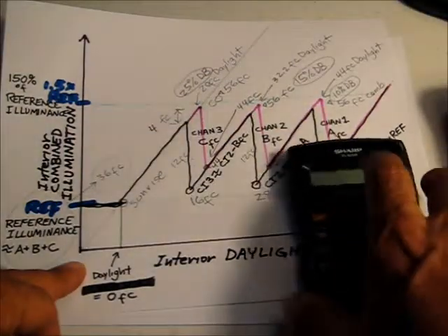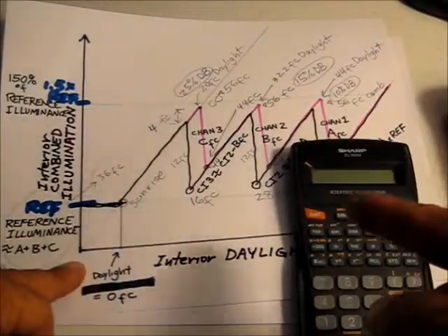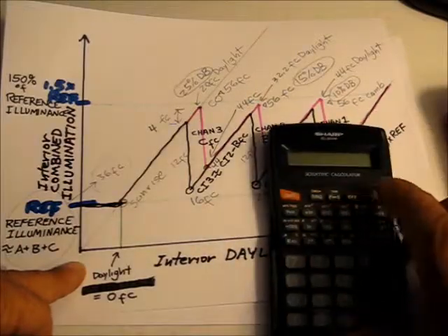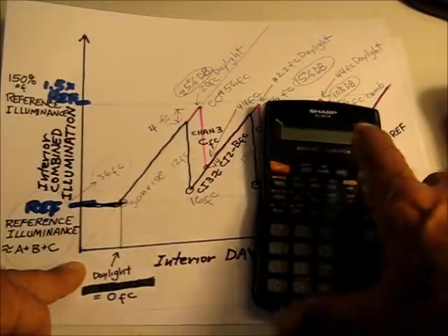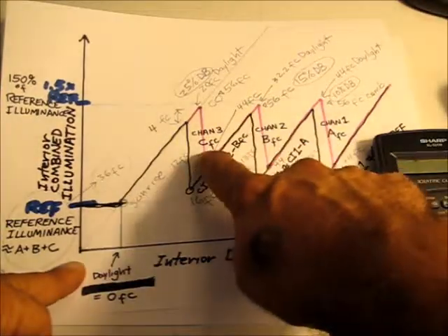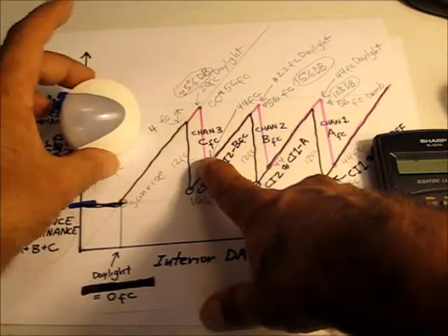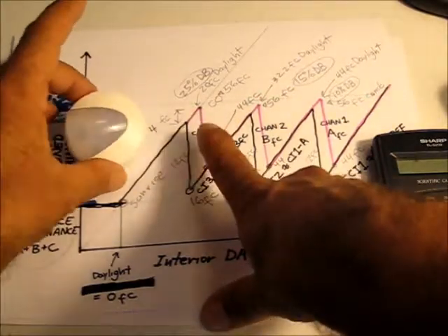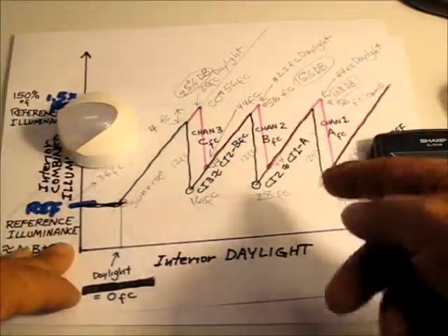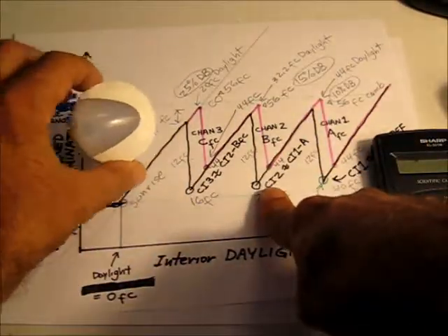You, as the commissioning agent, run a test on this system and discover that one stage is putting 2 foot candles on the system sensor. It's reporting, when this one comes on, I see 2 foot candles. Another stage may be putting on 6. Another stage, it might be seeing 8.